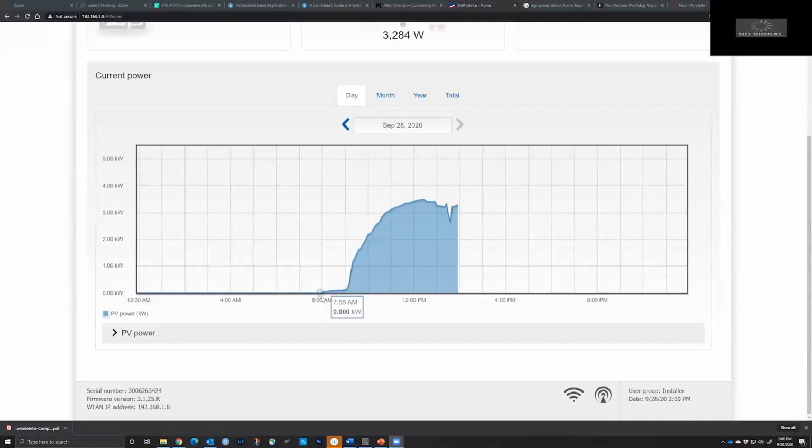It takes a little bit of energy to actually run the inverter, which converts it from DC to AC power. And so it doesn't really start generating electricity until the sun's quite a ways up in the sky at 9 a.m. in this case. And here it's generating 0.12 kilowatts. And so if it did that for an hour, it'd generate 0.12 kilowatt hours because it's 0.12 kilowatts running for an hour. If it did it for 2 hours, it'd generate 0.24 kilowatt hours.